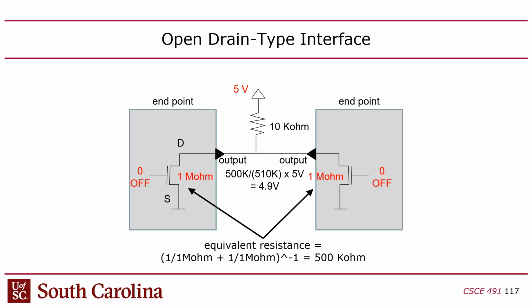So you have a voltage divider where the output voltage is going to be related to the bottom side resistance, which is a mega ohm, right, divided by bottom side plus top side, right? So because a mega ohm is so much higher than 10 kiloohms, the voltage here in this voltage divider is going to be pretty high, right? It's going to be almost 5 volts, right?